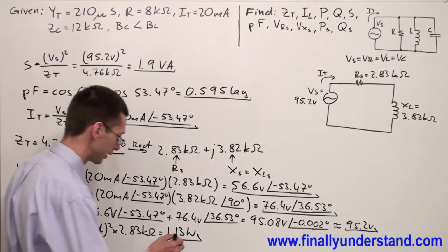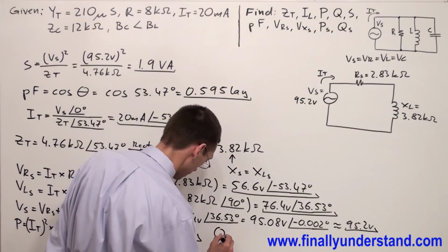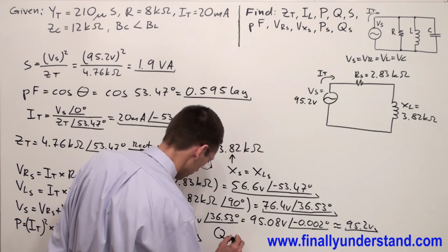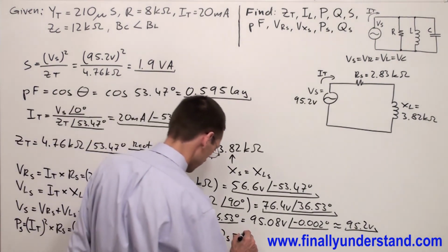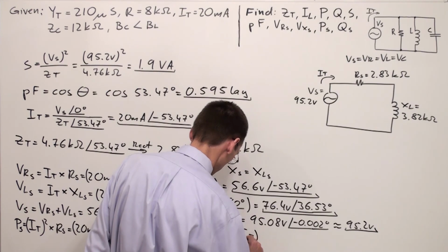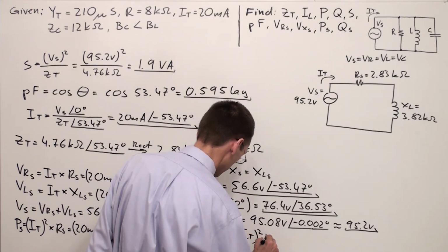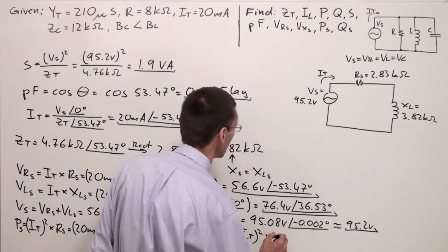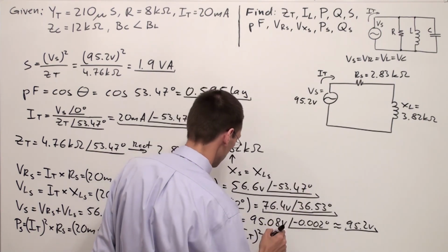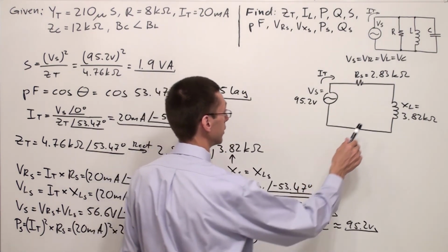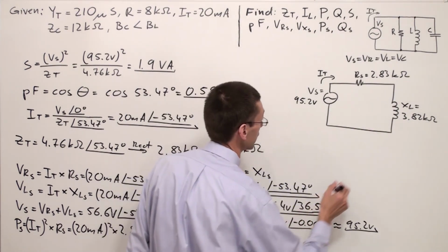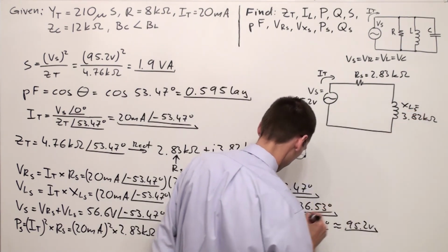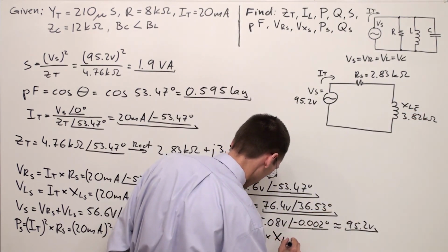Next, we are going to find the total reactive power in the series equivalent circuit. Of course, this was the true power in the series equivalent circuit. So this is nothing else, just I total raised to the second power times the total reactance in the series equivalent circuit, which is simply X_LS.